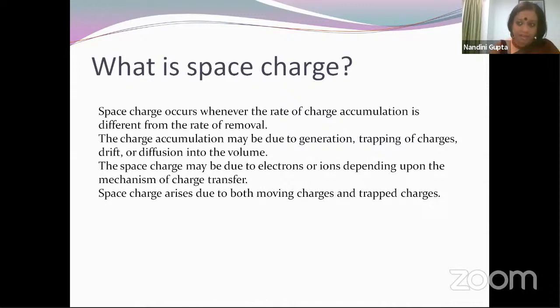In the lecture on aging, I talked about degradation mechanisms and damage mechanisms, where certain physical and chemical processes happen within the dielectric, which do not show up as visible signs of defects, but which cause continuous degradation of the material, causes aging.